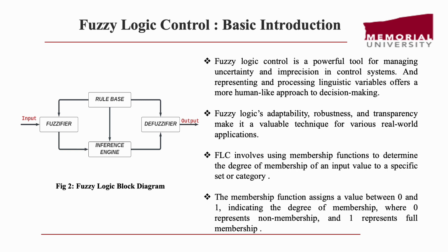So basically, the fuzzy logic which we have used in our project is for power system applications, especially in wind power generation. It is a type of control system which takes more human-like decisions, and the membership function assigns a value between 0 and 1, indicating the degree of membership, where 0 represents non-membership and 1 represents full membership.